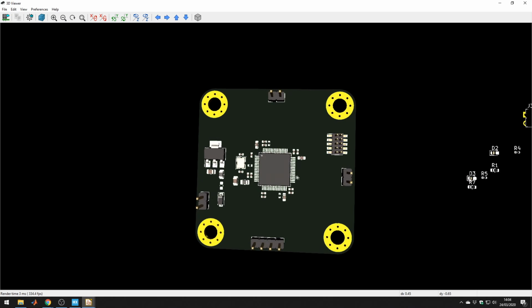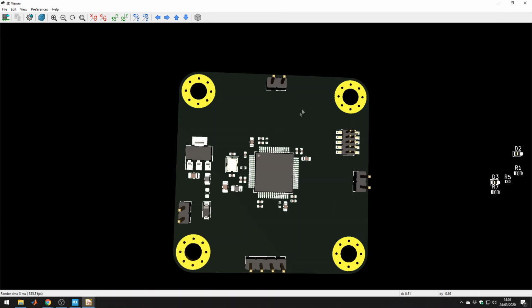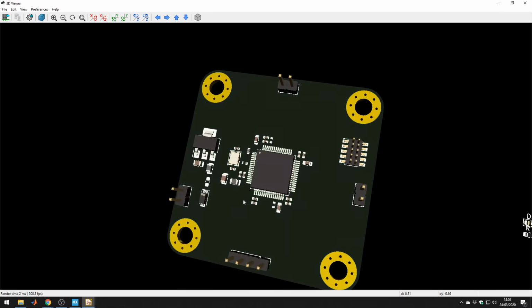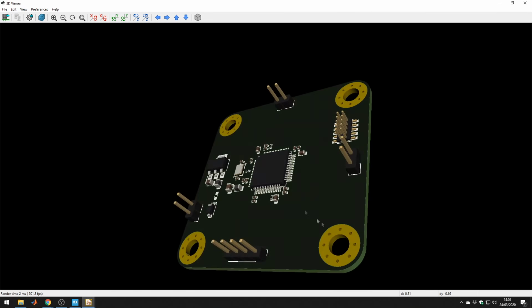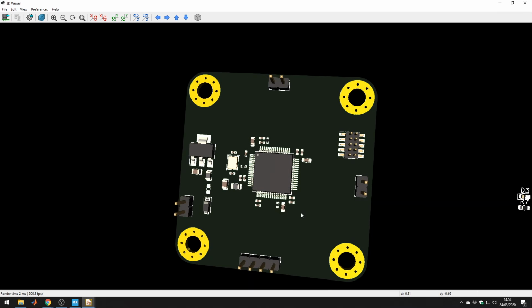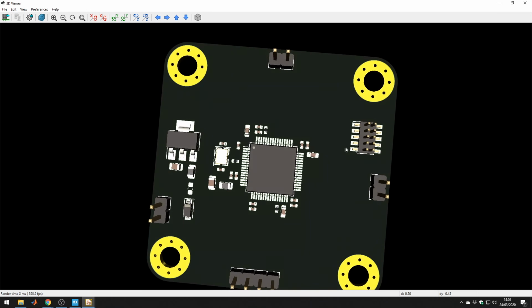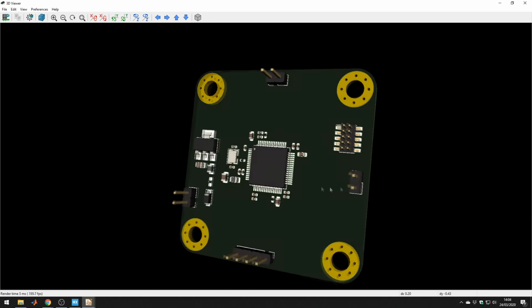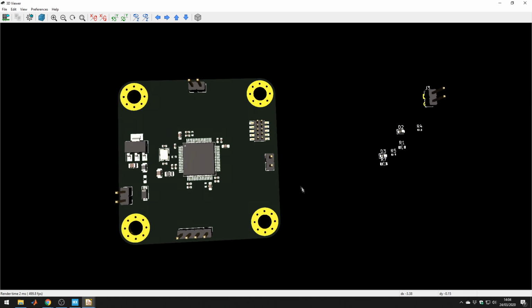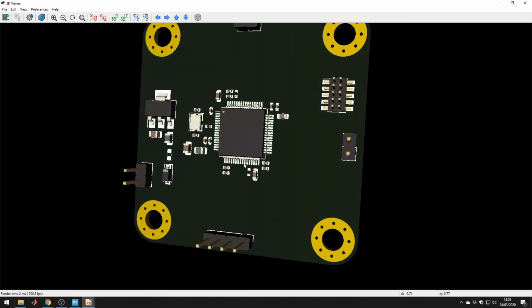Okay. Again, I tend to use the 3D viewer just to make sure everything looks kind of alright. I mean, yeah, here it's not entirely the nicest, because here it might be a bit cramped. There's lots of empty space here and here. We could have made the board much smaller, that's the thing. A 5x5 board is far too big for this, but you know, if you want to add more pins, more pin outs, you can do it with this size of board. You can have more connectors on the edges and so forth. Of course, if we take the mounting holes away, this will make the board a lot smaller as well. But for the sake of just, you know, just getting done, because the main point of this video is to just get a working hardware design, which you can then repeat and do your own stuff with, this will do.